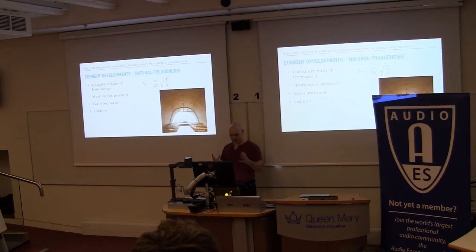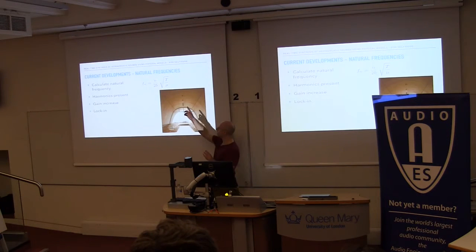One of the other major factors in aeolian tones, when wind's hitting wires and cables, is natural frequencies. The natural frequency is relative to the tension, the length and the mass density. But basically, if you recall, I was talking about the vortices shedding. Well, when they match the natural frequency, the gain is greatly increased.